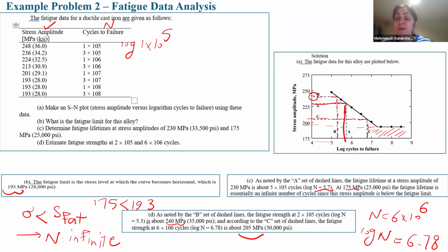To summarize what we talked about today: fatigue failure is one of the most important considerations in design because it occurs gradually and often without any warning. So it's very important to consider the fatigue behavior of materials. Understanding fatigue behavior, especially the rotating bending test that we talked about today, and how to interpret the S-N curve helps engineers design safer and more durable components.